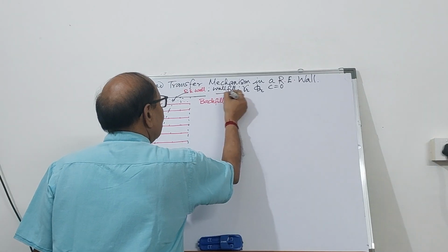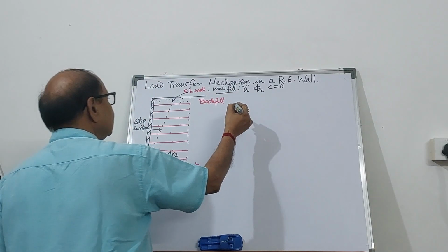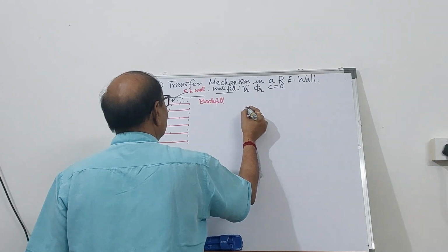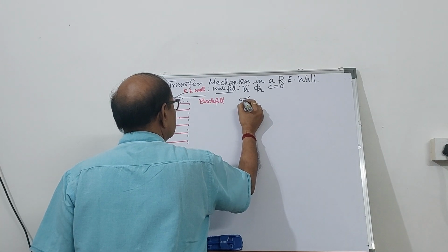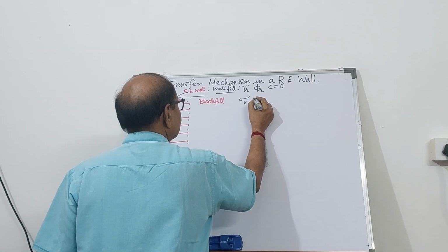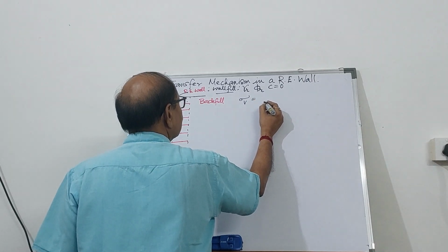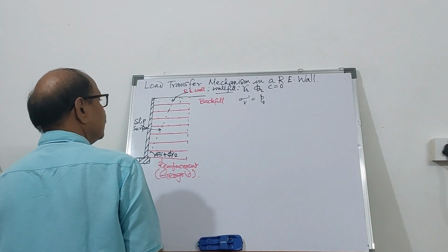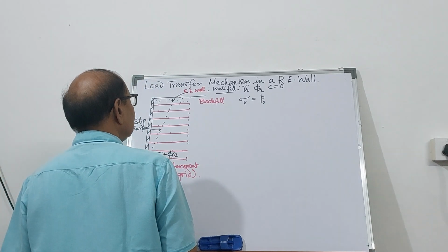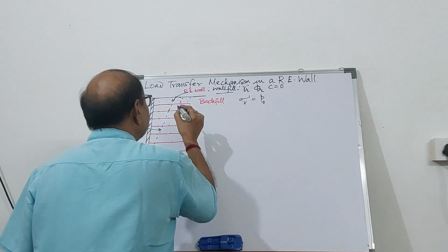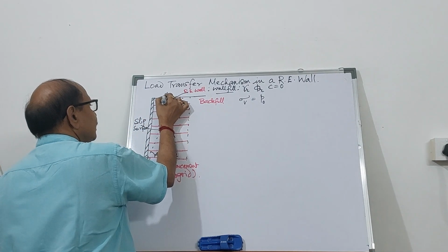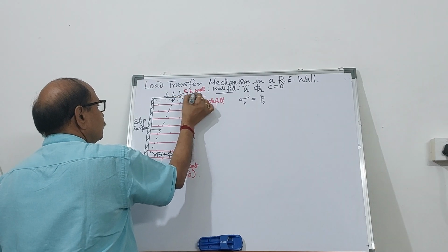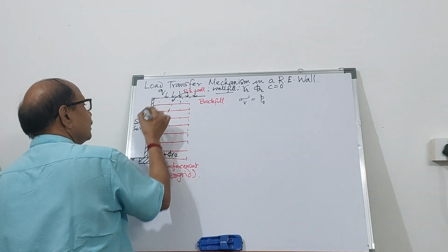Now, due to this wall fill material, what is the vertical pressure? The vertical pressure here is due to overburden, isn't it? The vertical pressure is due to overburden. And if there is a surcharge, let's say you have a surcharge, and this surcharge is q.